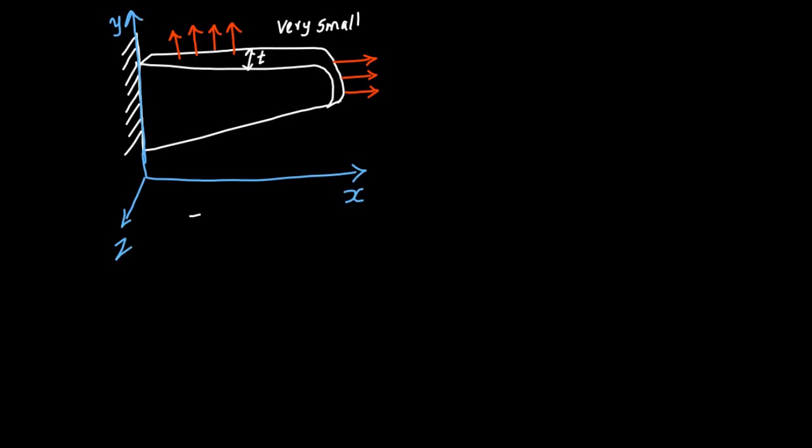Now, if you want to analyze a structure like this, you can actually discretize the cross section of this particular structure into many small triangles. So what is the cross section that you are bothered about? Well, this is the cross section that you are bothered about, the one that I'm putting yellow in color, right? So that is the cross section, and you can discretize this into many small triangles. See, that's it. You can discretize this into many small triangles. I can go on doing this, but of course you are getting the logic behind it, right?